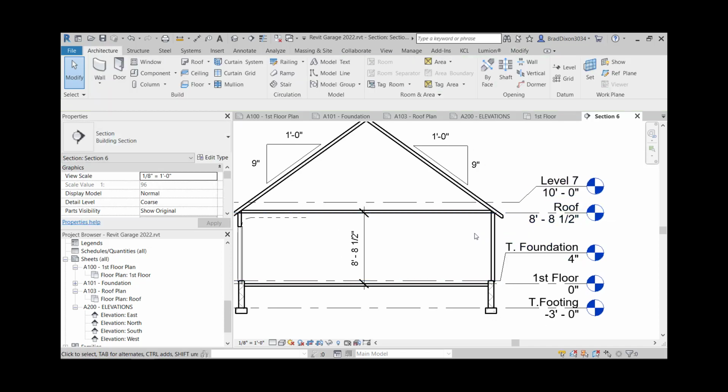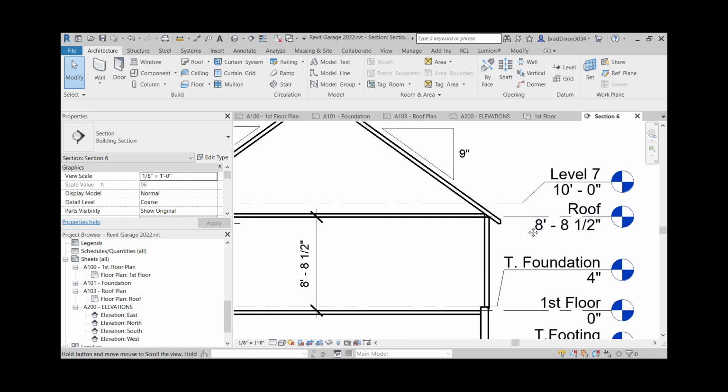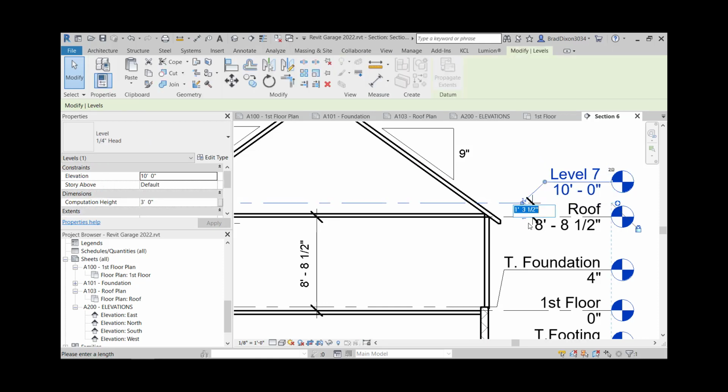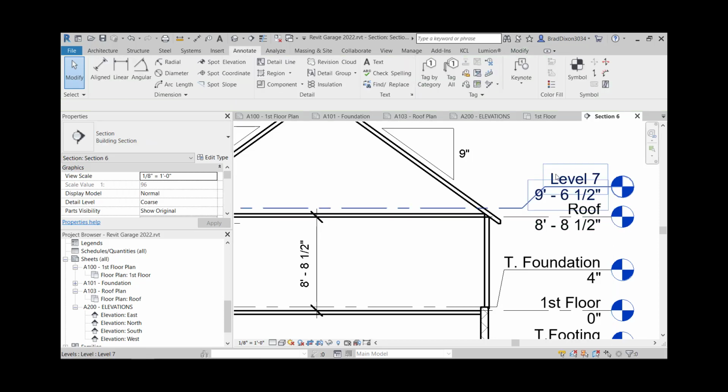And what I want to do is make the bottom chord of this truss 10 inches thick. So we're going to use 2x10s, which are 9 1/4 plus 3/4 inch plywood. So that's going to end up being 10 inches. Rather than do the math there, I can also just throw a dimension line on between those two, click on this one and click on the text, say 10 inches. And I just delete that. So now I know that my level